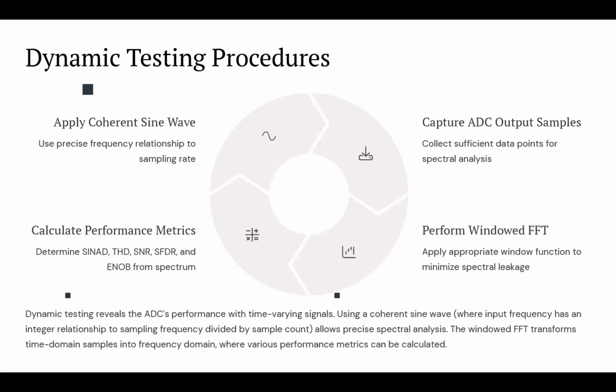Again, the equations for calculating these specific parameters, SNR, THD, all of them, are mentioned in the standards precisely. You need to follow those specific equations, because for example, THD has different types of equation based on what you need. You might want to define the THD in decibel units, or as a percentage, or as a per unit. Okay, the equation would be different. So in this standard, we use the decibel one.